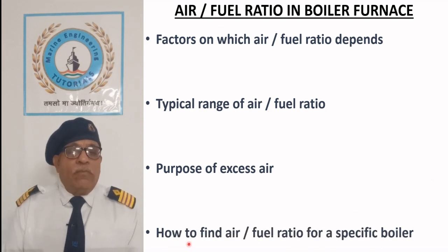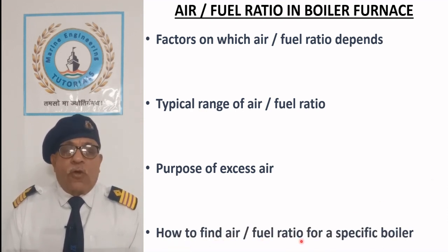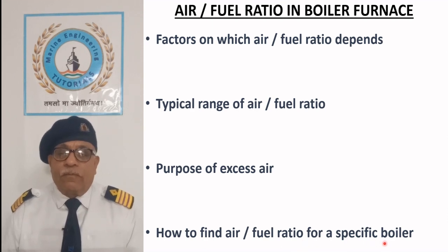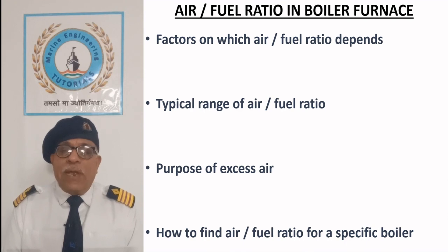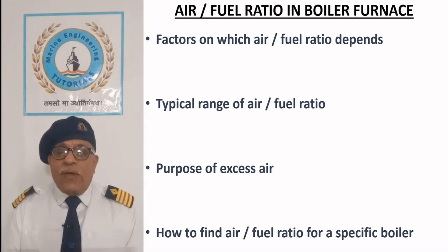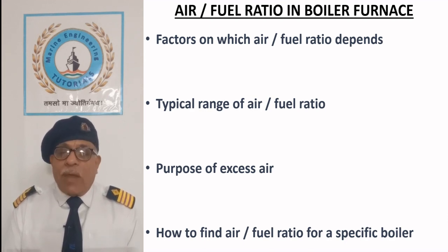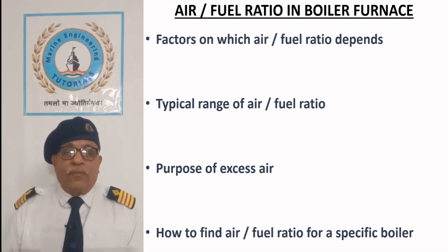How to find air fuel ratio for a specific boiler? Boiler manufacturers carry out comprehensive tests on the combustion of fuel in boiler furnace at various loads and document the most appropriate value of air fuel ratio in the boiler's instruction or operational manual and provide the boiler performance curves.